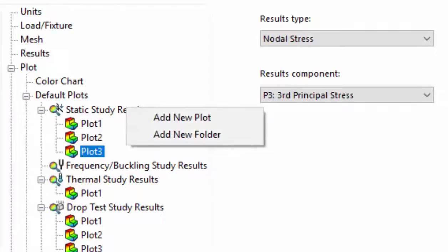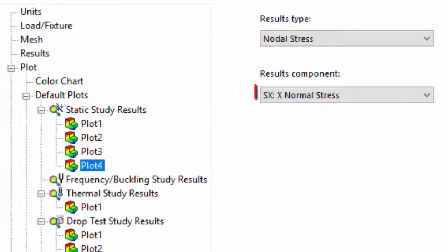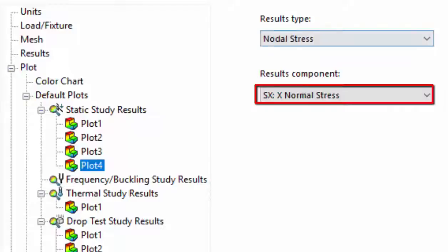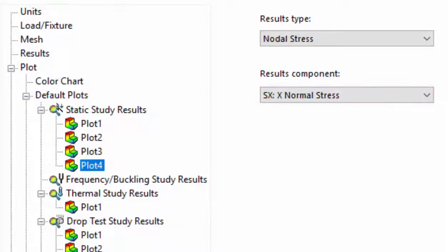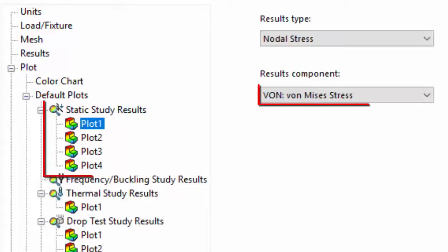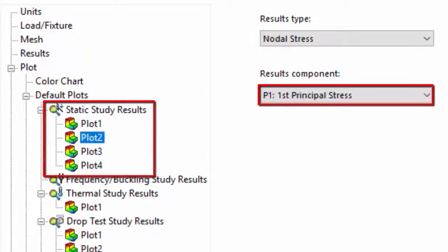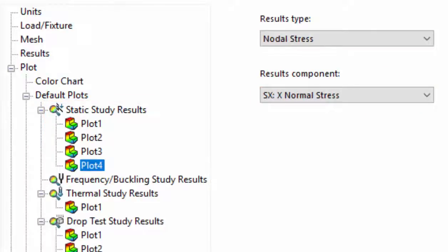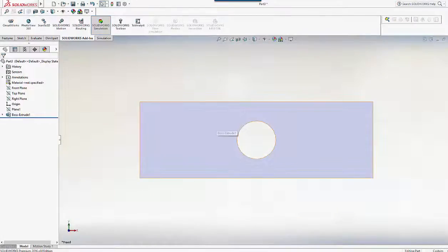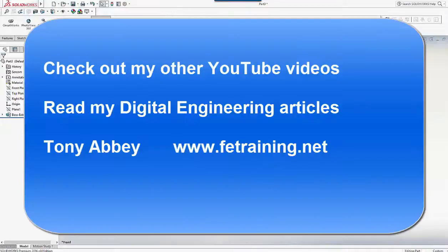Finally, we can set up the Cartesian stress. The default is the x direction, and I'm going to be flipping through x, y, and z. I'm not going to be setting one up for each of those. So that's all set up then, and finally we can easily flip between these stress states in any analysis result. I'll be explaining how to create a roadmap for stresses and the other material on the course. So we're good to go, so I hit OK. We are now ready to open Simulation to create a new study to explore mesh convergence, and we'll look at that in a later video.